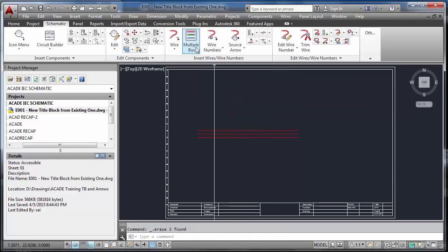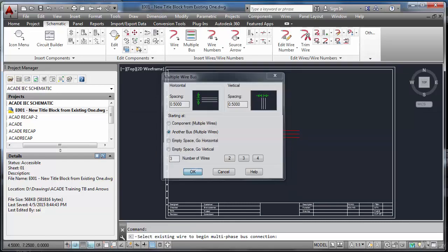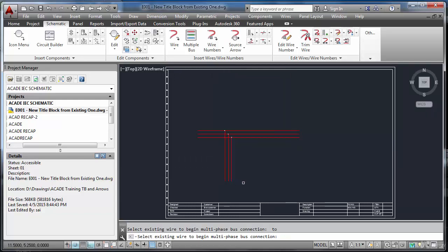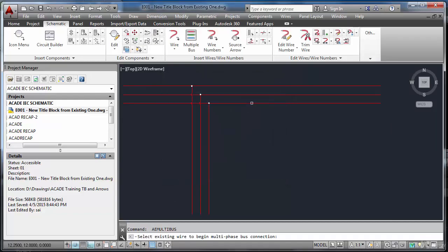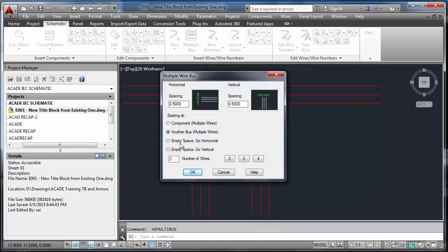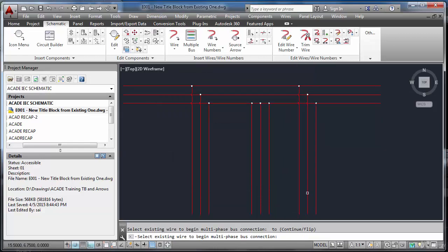And from a wire, if you want to draw from a bus another one, just select this first bus in this way. Don't select the bottom one. If you select this one, see, it will be drawn in this way only. Always select the top one in this fashion. This is how you should select the bus bar. In order to trim the wires, you should use this arrow.